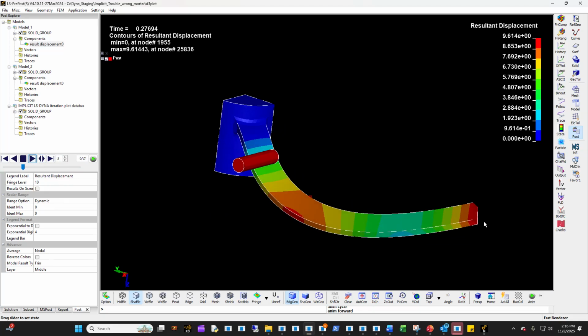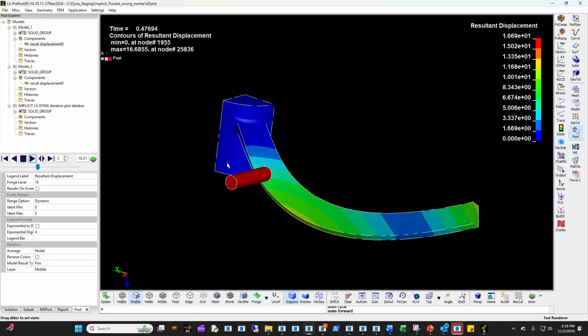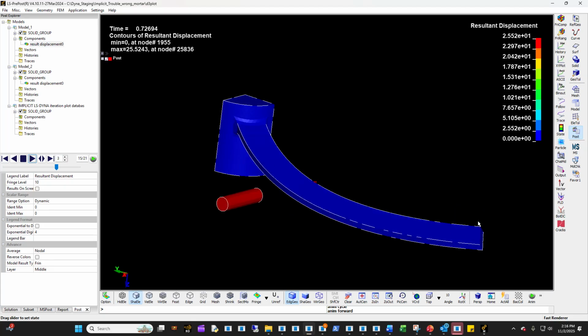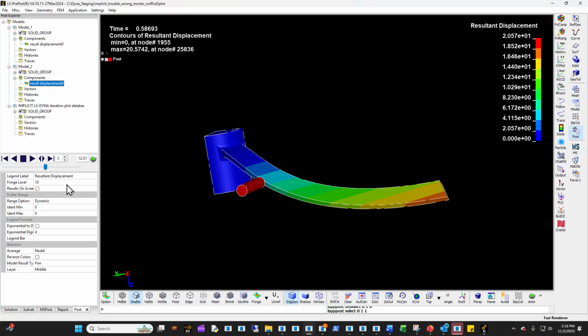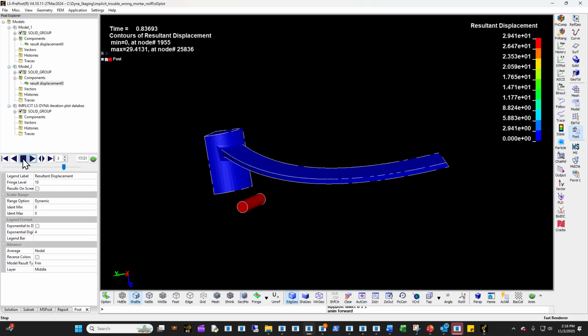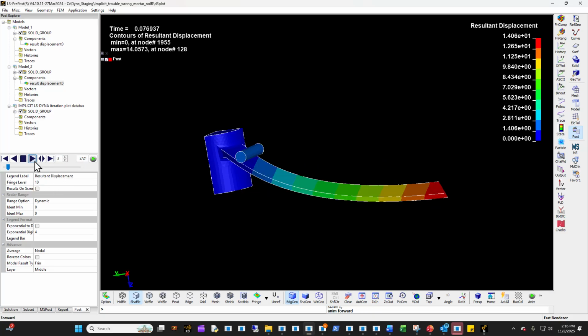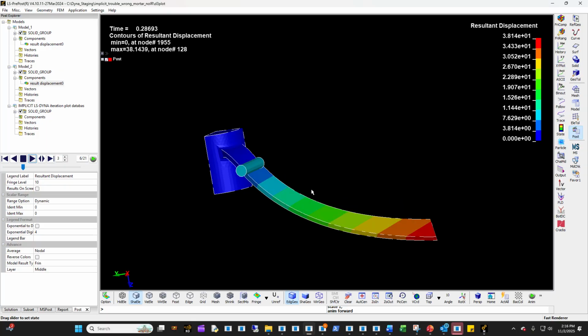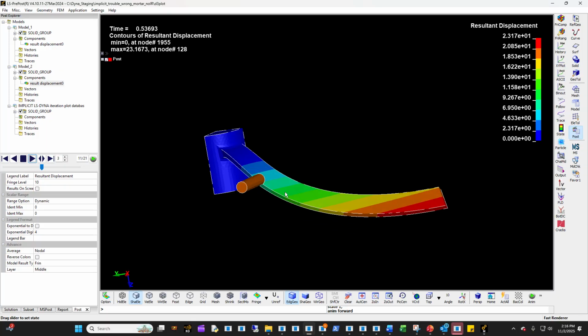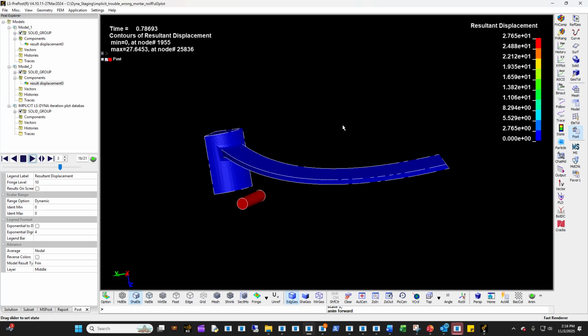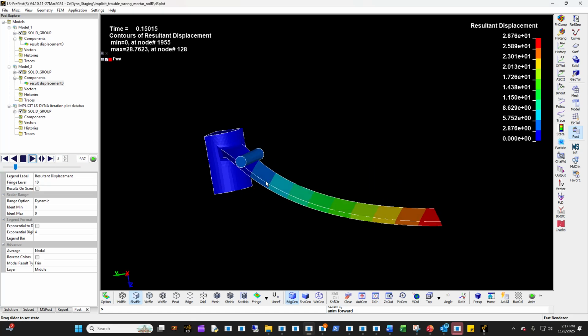So you see this mode right here has that little going upwards mode because I use inertial relief to kill some of the initial modes. In this case, I don't have any initial mode, so you actually get the correct responses. You do not want to use inertial relief. That's the key point, right? If you want to use it, you have to be very, very careful. For this problem, it's certainly not applicable, which is one thing I have to sort of demonstrate. I'm hoping I'm demonstrating right now, right?